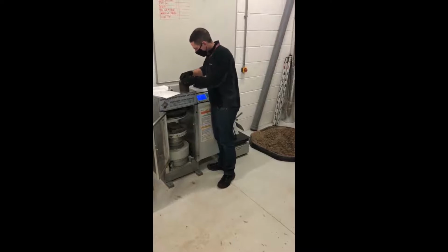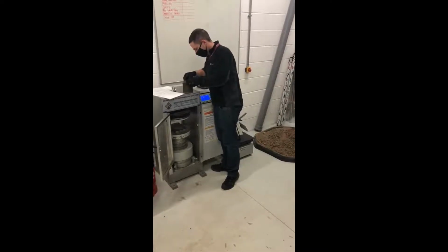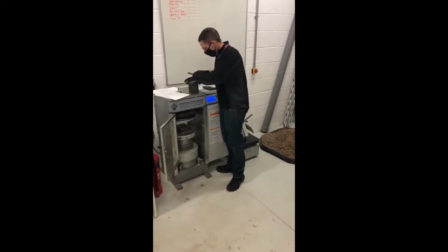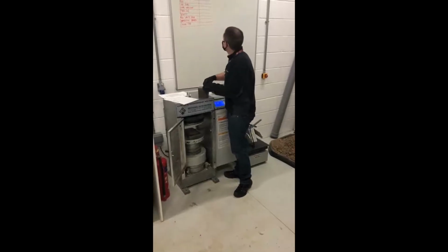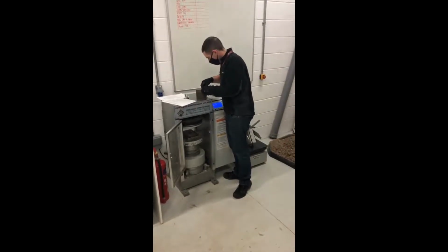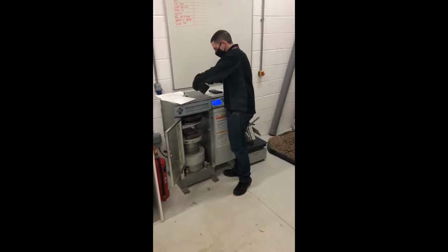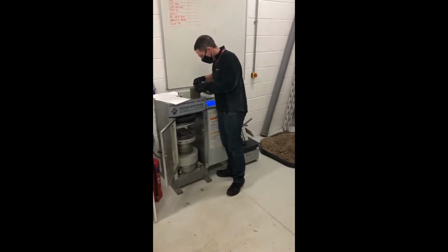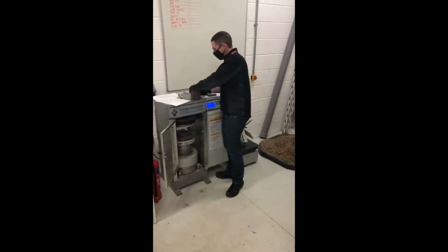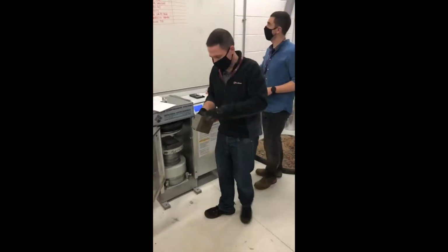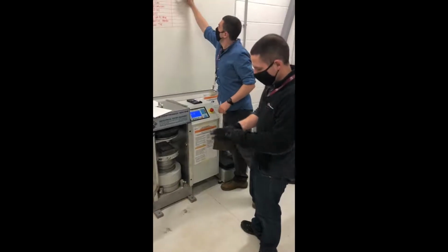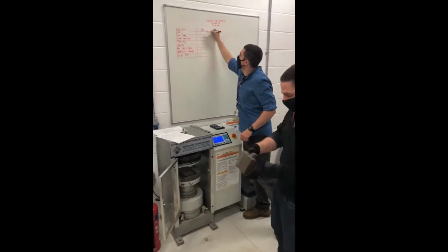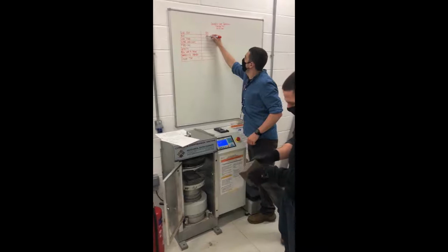So that's 100mm. 100. Also do that with calipers. 100. Yeah, you could do that with vernier calipers, which will give you a more accurate result. However, for the purposes of this video today, we'll just use the steel rule.